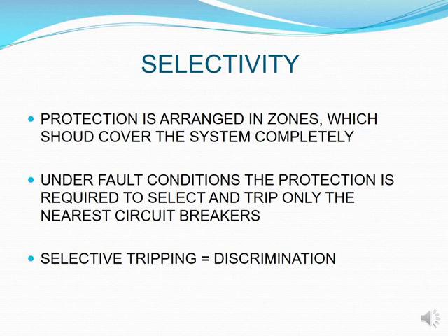That way your customers from the substation up until as close as possible to that 80 kilometers would still have supply of electricity and not all be taken off. This selectivity can simply be done by the way that we looked at discrimination.